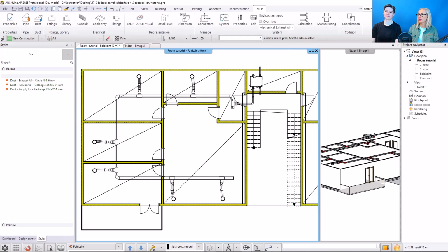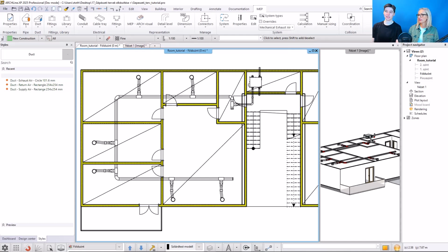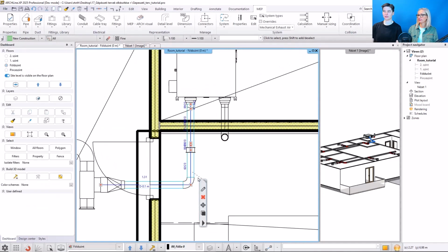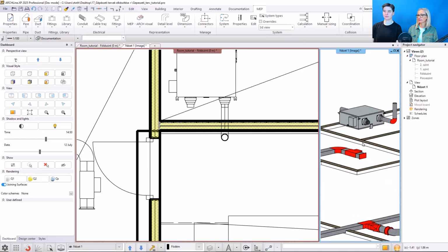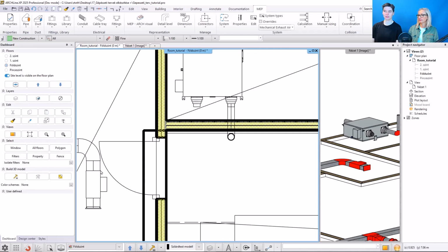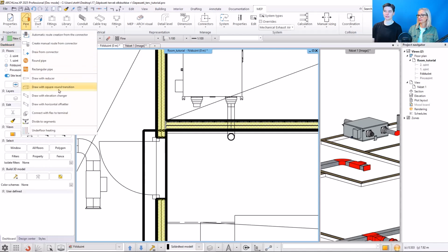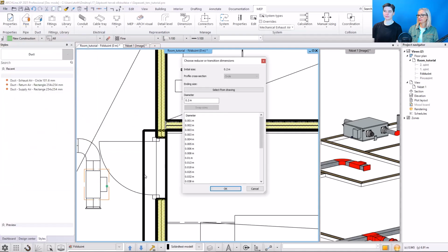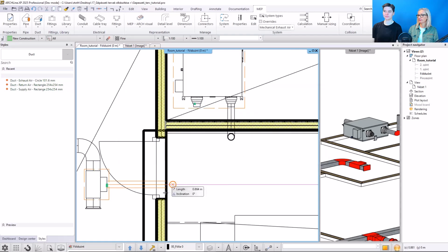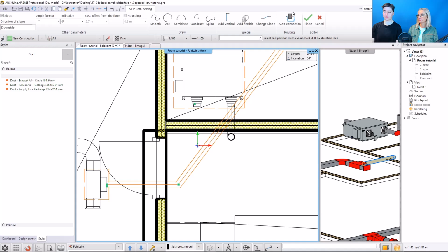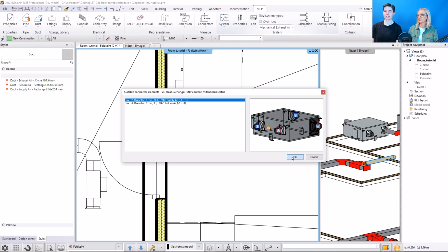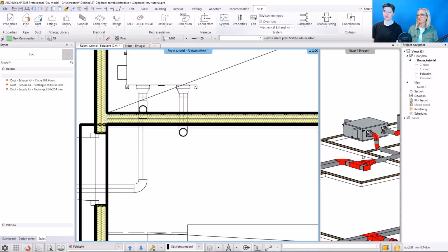Okay, is there a quicker alternative for manual connections? Yes, there is. Instead of manually placing each pipe, we can use AutoConnect. Place the transition fitting. Select AutoConnect, click the connector, and the program does the rest. It automatically generates the pipe path and adds necessary fittings.